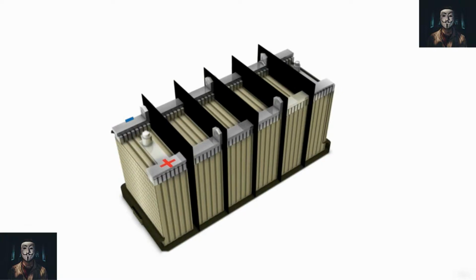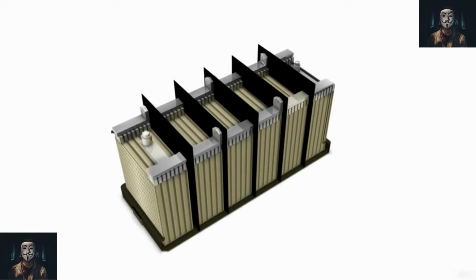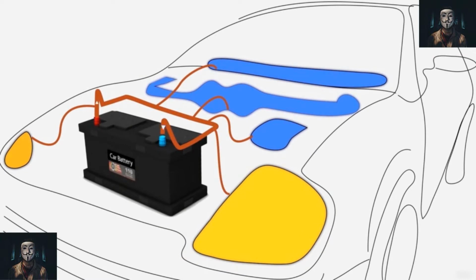Another measure is the cold cranking amps rating, which is a measure of the maximum current that can be supplied for a period of 30 seconds before the battery voltage falls below 7.2 volts. This is carried out at minus 18 degrees centigrade, so that it represents the most severe condition of cold engine starting. The cold cranking amps, or CCA, rating of a battery is an important measure in regions that suffer very cold winter temperatures. Some maintenance-free batteries incorporate a built-in hydrometer to indicate the state of charge and the condition of